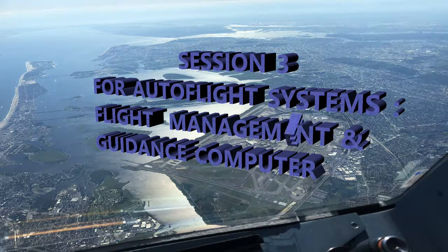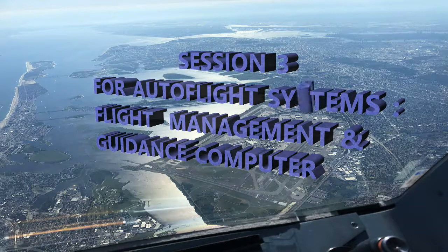And then of course you have LRU identification, which can be obtained after the power up test is done. But you have this on ground only. It's going to get the part number of the FACs and also the part number for the FMGCs. It's also going to give the aircraft identification there. And then your ground scan, you can get that from the MCDUs.